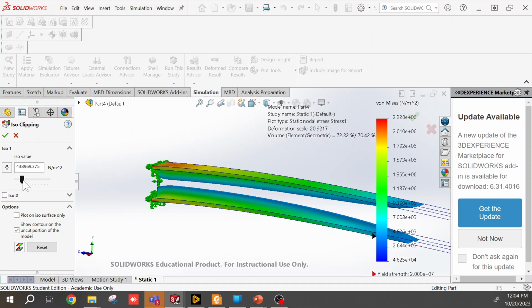So technically, this will kind of tell you that if you wanted a mass optimized design, it should be kind of tapered. You start really wide at the base where all the stress is, and you taper it, which isn't really typically how diving boards are made. They're typically constant thickness, and that's because you have to walk on them. But if you ever look at Olympic diving boards made out of concrete, typically they're made like that. So there is some validity to what we're seeing here.